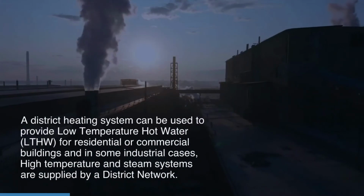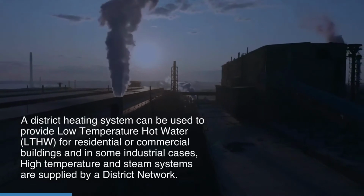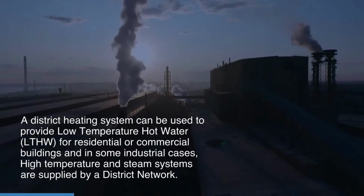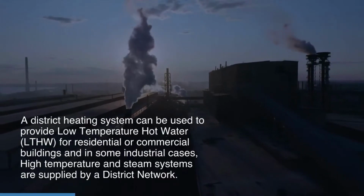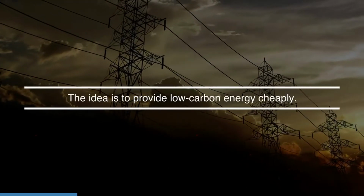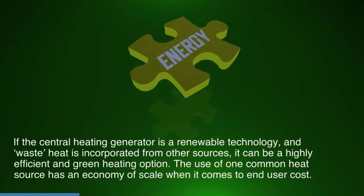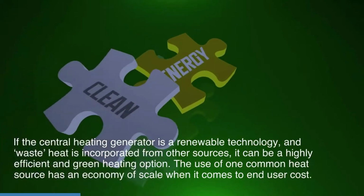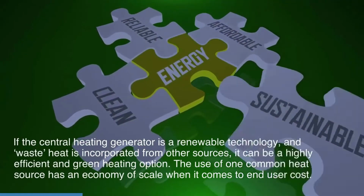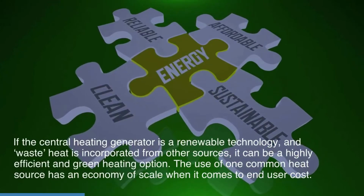A district heating system can be used to provide low-temperature hot water, LTHW, for residential or commercial buildings, and in some industrial cases, high-temperature and steam systems are supplied by a district network. The idea is to provide low-carbon energy cheaply. If the central heating generator is a renewable technology, and waste heat is incorporated from other sources, it can be a highly efficient and green heating option. The use of one common heat source has an economy of scale when it comes to end-user cost.